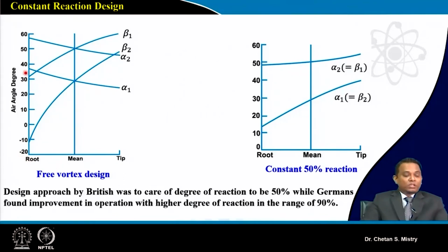And as we have discussed, if you look near the hub region, we will have a great variation of blade angle or blade deflection angle. So if you look near the hub, my delta beta will be large. And if you look near the tip region, my delta beta is going to be slightly lower. But overall, this is giving me a highly twisted blade.